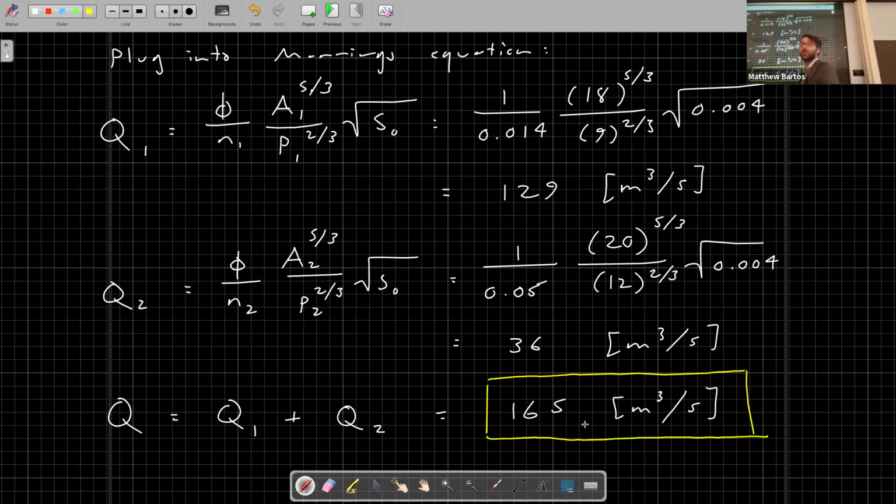Right, so there will be a homework problem on homework 6 that is pretty similar to this one. So make sure you're comfortable with this approach. To compute the discharge in an irregular channel cross-section, we just break it up into pieces that we can analyze, and then we add those individual discharges together. So this is actually the same way that the discharge would be computed in a computer program like HEC-RAS, which you'll be looking at in Lab 5.